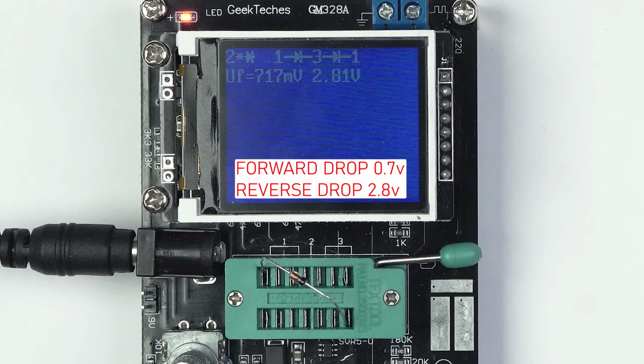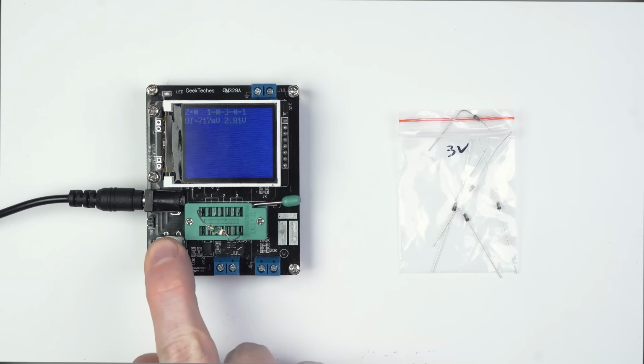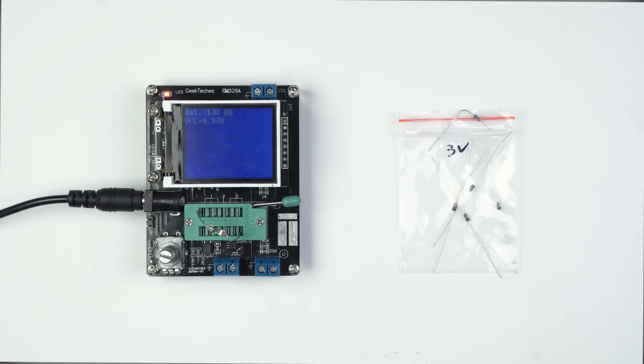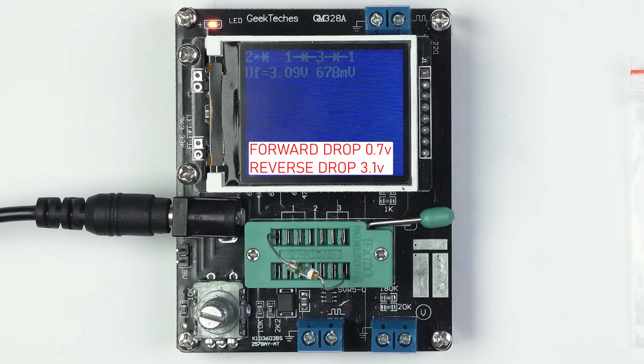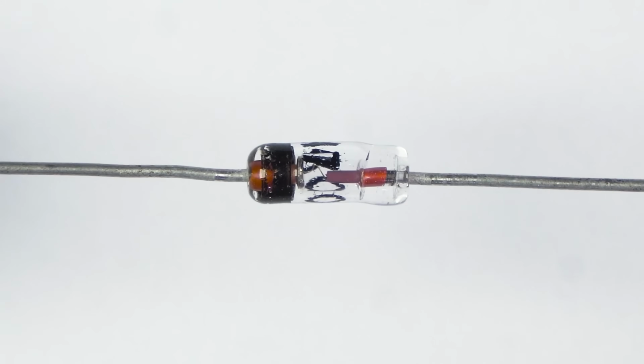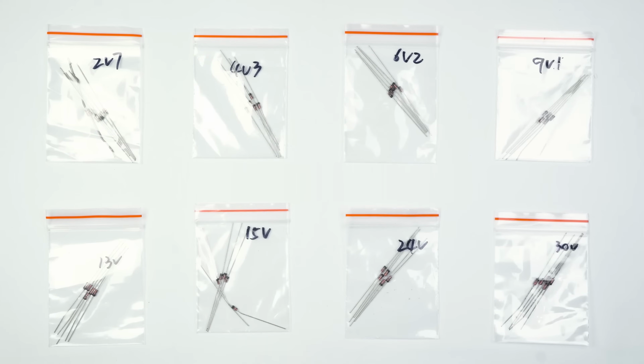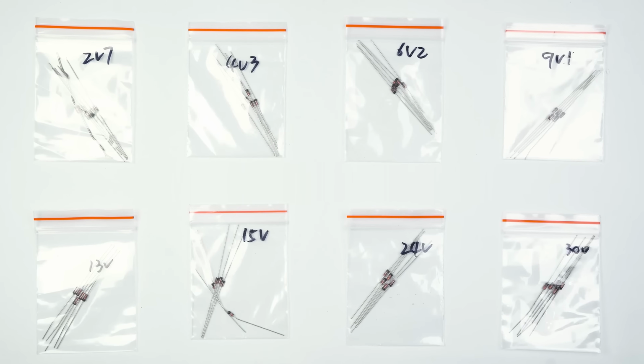So the working polarity of a Zener diode is reversed, and its anode is usually connected to the negative power rail. In most cases, you can find out the voltage rating of a particular Zener diode only by the designation on the package, or by measuring it with a metering device, for example, the already mentioned GM328 universal tester. Most Zener diodes cannot be measured with a multimeter because the voltage across the probes is not high enough to reverse bias the component. You can also measure the Zener voltage drop with a regular voltmeter.